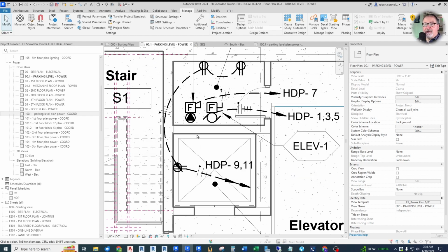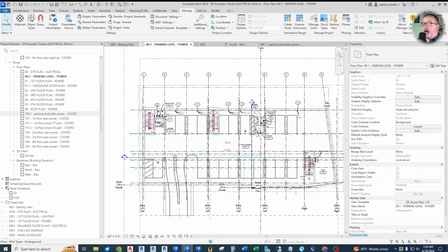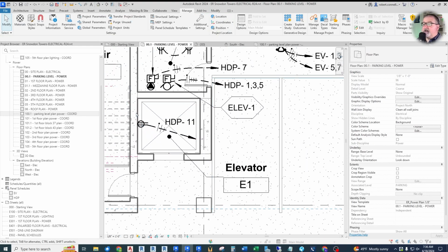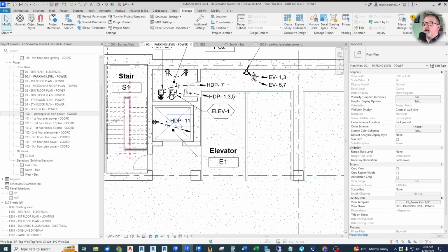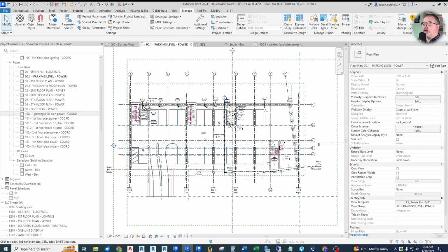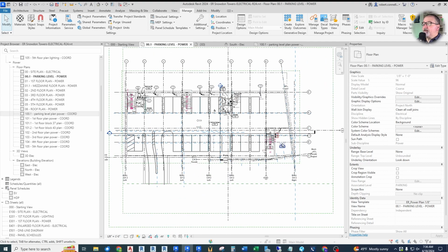Now, I just mentioned that circuit path offset. Well, what's circuit path? Well, behind the scenes, Revit is determining a circuit path, for example, and I'm going to disconnect these because I don't want two on this here. It's determining a circuit path from this receptacle to panel HDP, which in this case is way over here in our utility room. So here's HDP. Now it's not just figuring as the crow flies direct to direct. If you go underground, that may be appropriate. If you go overhead, it definitely is not. We typically try to follow structural lines, so we would go down and follow some lines.